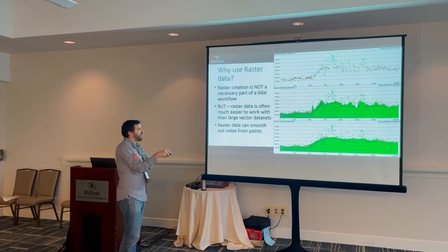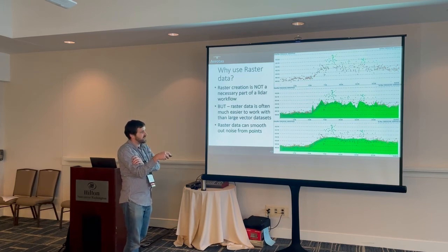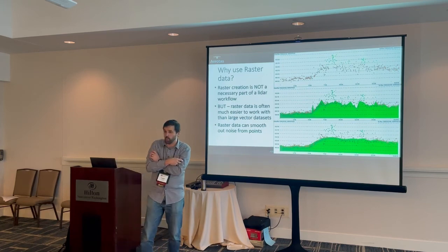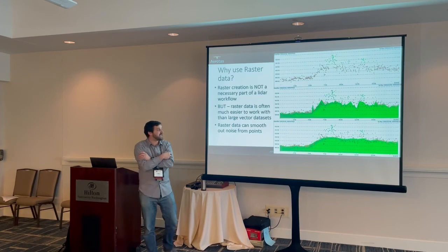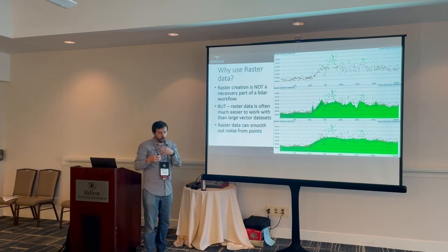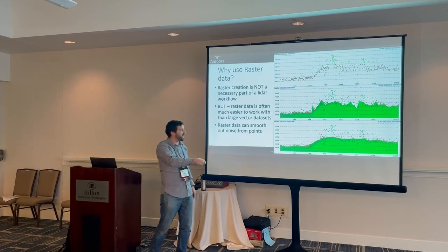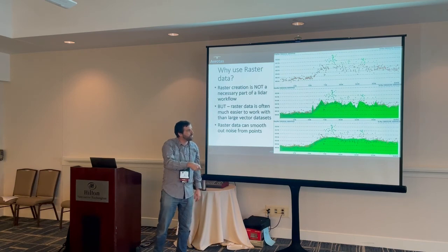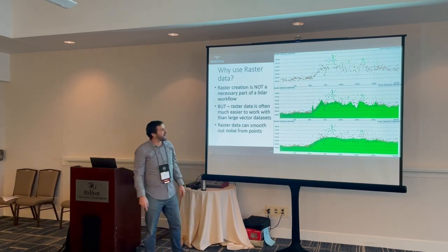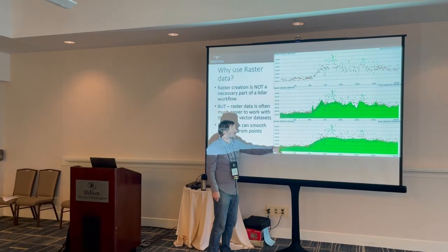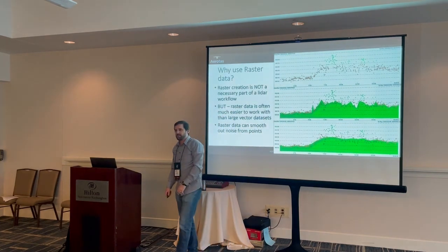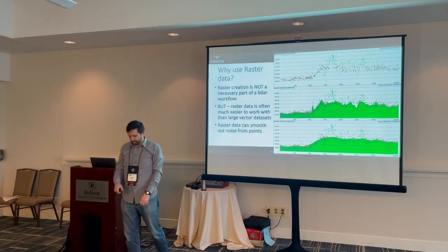Whereas if you rasterize it and have like a 1 foot bin size, it effectively smooths it into 1 foot bins and takes the mean of all of the hundreds of points within each individual bin, so it smooths it out. And our analysis after the fact has shown that this is a statistically more accurate surface than the noisy one is. Interesting, that is exactly what we do with hydro data.